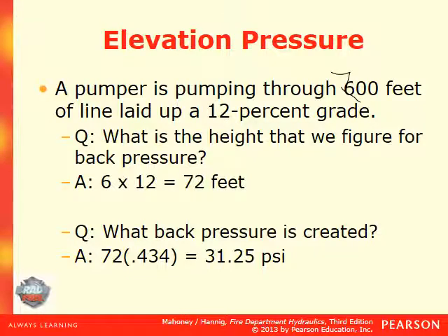What is the height? And we know a 12% grade per 100 feet is going to be 12. So 7 times 12 equals 84 feet.